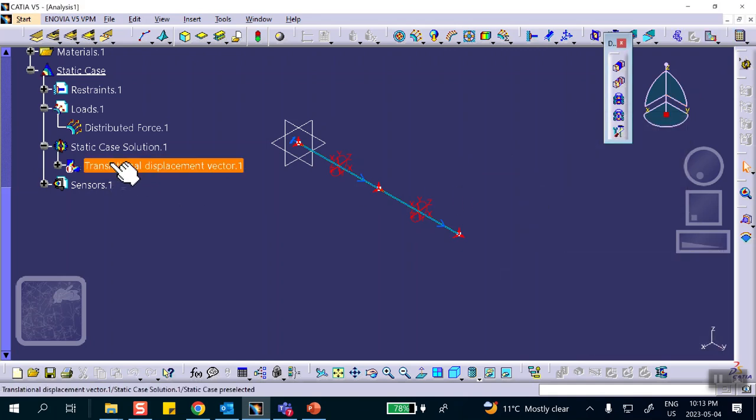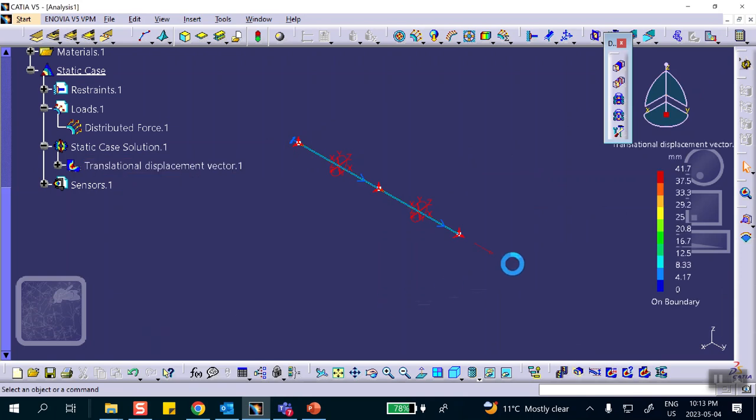Okay, good. If you look at the maximum displacement, obviously it's going to be different, right? Because if you put in 1 Newton at this node, you're going to have 375, because it has to fight two springs. If you put 1 Newton at this node, it's going to have to fight only one spring with a stiffness of 24. So 1 divided by 24 is going to be this one, times 10 to the minus 3 in meters.